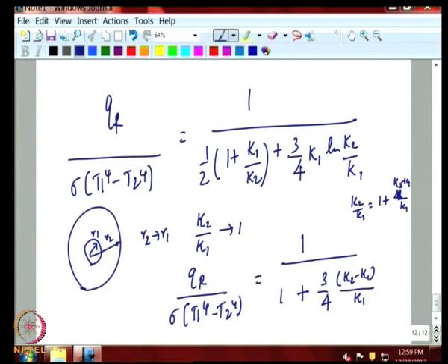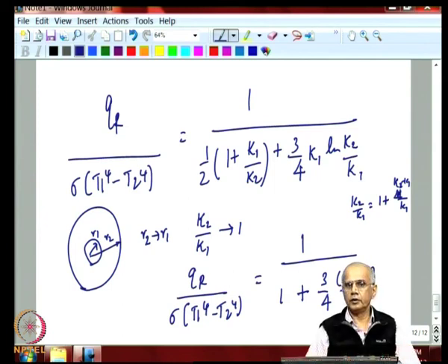So, in those problems, like if you want to deal with diesel combustion chambers where there is no R1 really, there is only R2, so R1 tends to 0. So, this term is going to 0 here. So, then this will dominate your result. So, we took a very simple example of radiative transfer in the thick limit of a cylindrical geometry and showed that there are similarities as well as differences. The similarity is in the method of solution. The difference emerges because of the fact that the radiative flux is not a constant in this case, although we are talking about radiative equilibrium.